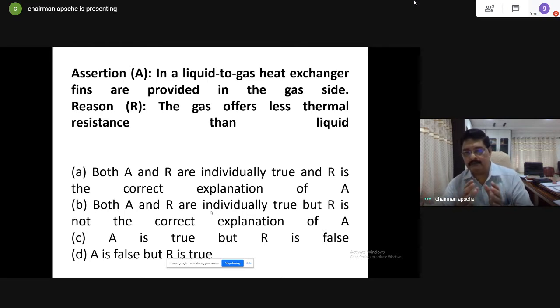Now, why do we use this thermocouple? That's where I said (T minus T infinity) divided by (Ti minus T infinity) is equal to e to the power of minus hAt divided by rho Cp. The temperature distribution equation of a lumped body can be used to define the time constant of a thermocouple, and that's where I use the concept of reducing the initial temperature difference by 63.2%.